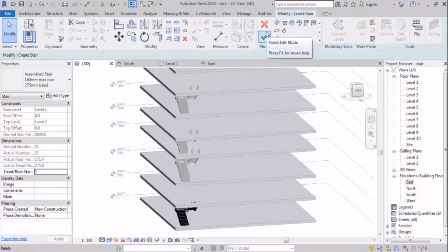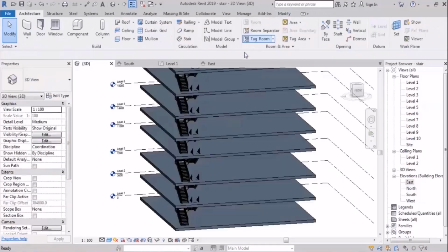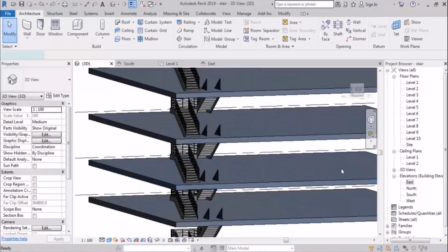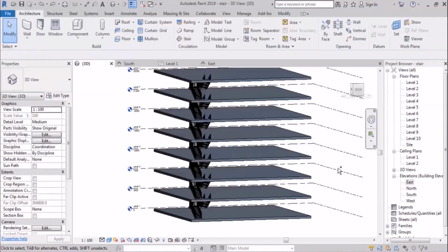So, if you have a change of height in any staircases or unpin any of them, they will not be edited with other staircases. These are the points that are necessary to know if you want to increase the number of stairs. So I undo and we go for the last subject.